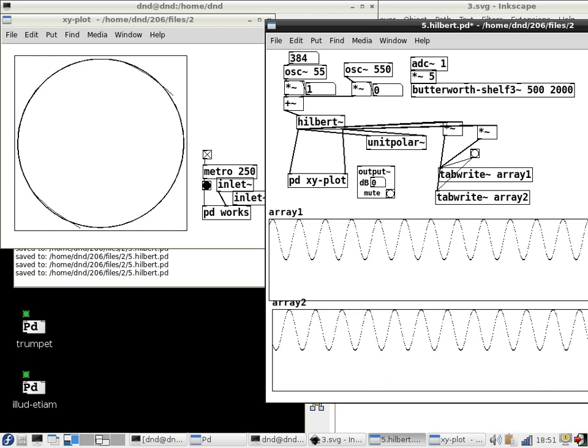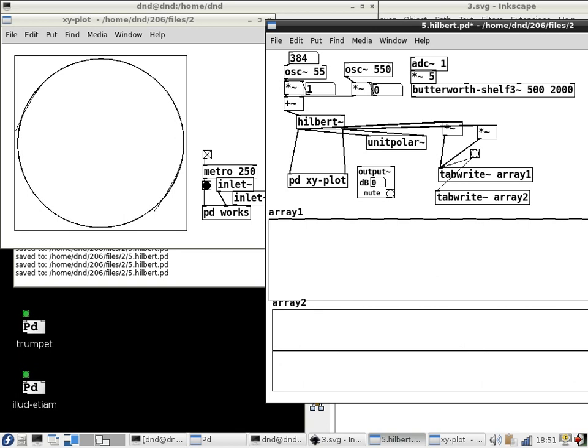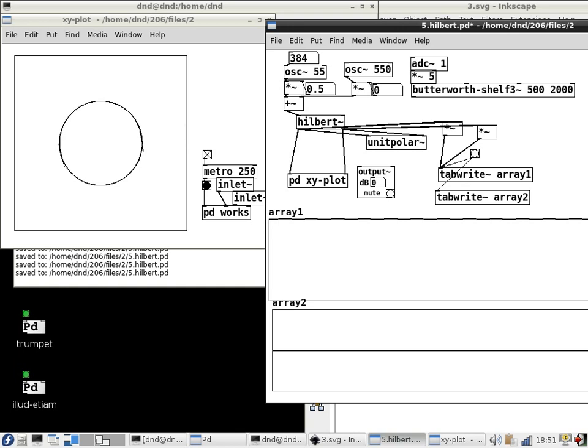You'll see two signals which, if you added those two signals up, would give you a constant, like this. There, I'm adding them up, and there's a little bit of not exactly roundness, but basically what's coming out is a constant, which is the amplitude of this oscillator. Actually, the squared amplitude of the oscillator. If I now set the amplitude here to 1/2, this goes down to 1/4.